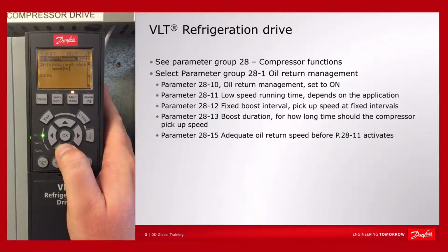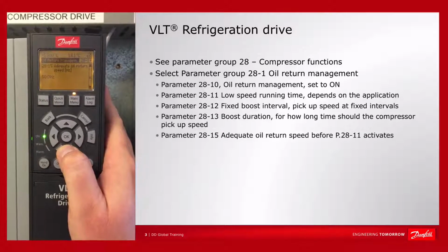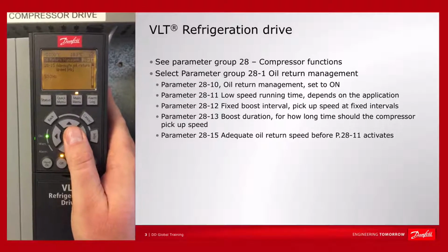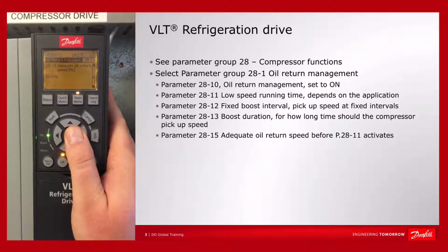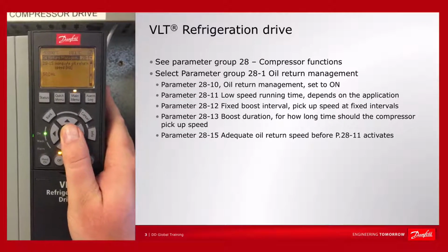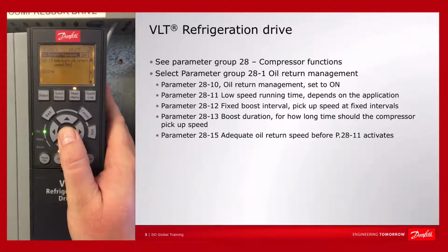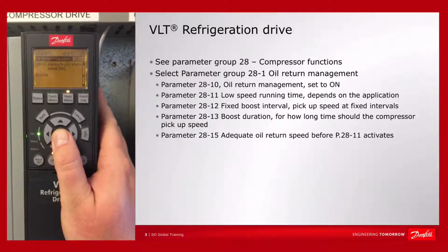Then you must determine at which speed oil is returned adequately to the system. At speeds below 50 Hz, oil is not returned adequately to the system, so we will leave this as it is. It could be 40 Hz, it could be 55, depending on the compressor and the system.